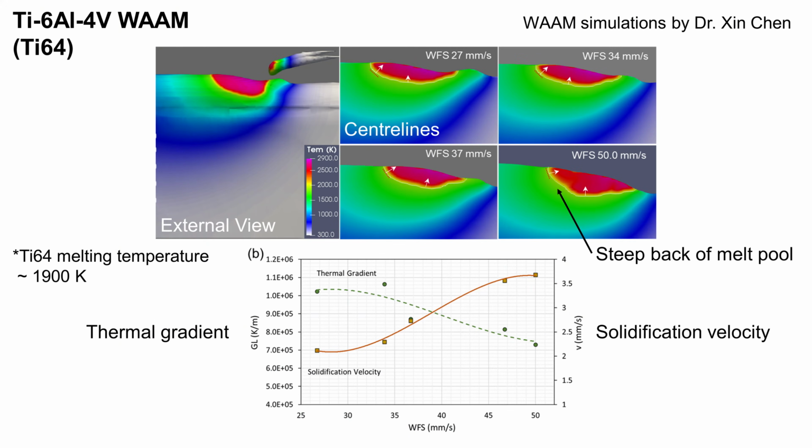Increasing the wire feed speed was supposed to lower the thermal gradient in the melt pool, create more undercooling, and activate the CET. This is what Shin's simulations were supposed to prove, but they didn't. Not really. Instead of predicting a significant decrease in the thermal gradient when trying to deposit a higher volume of wire, what we found instead is that the process self-compensates for the higher wire feed speed.